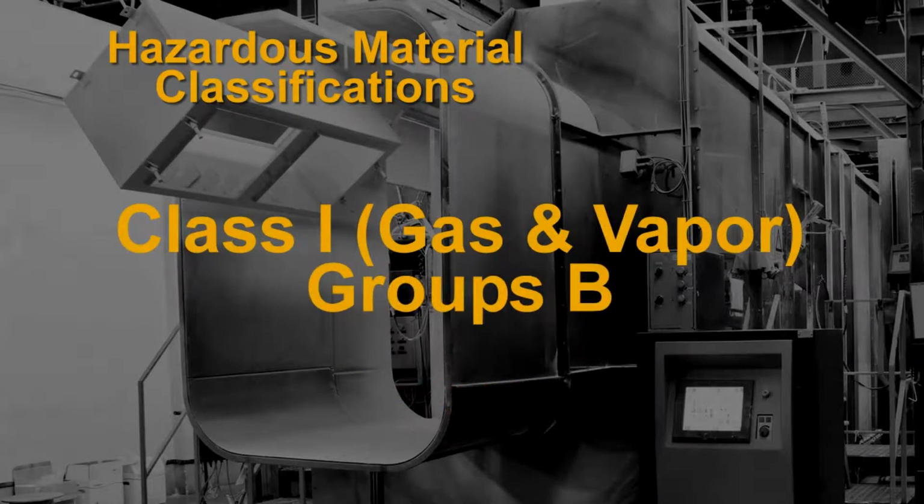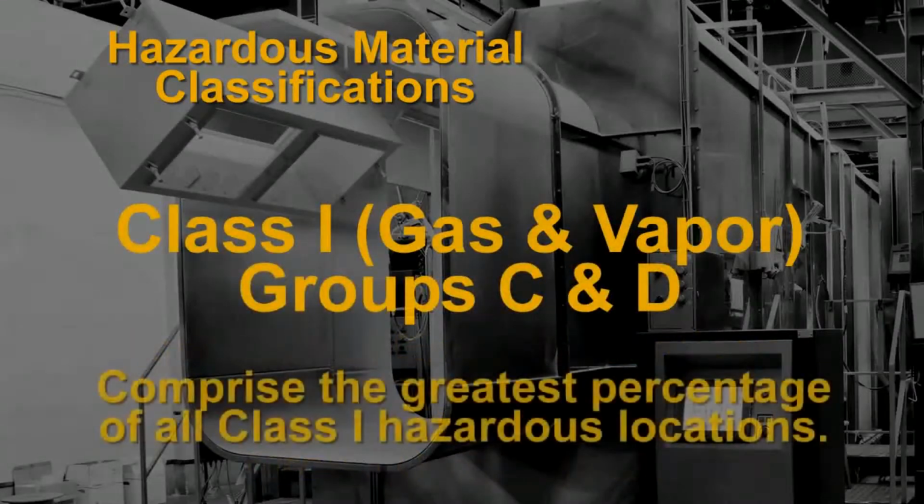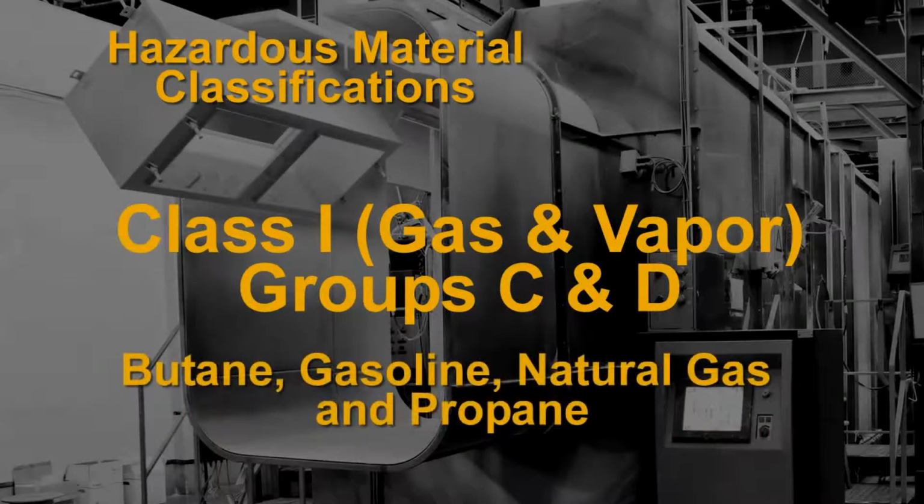Group B is another relatively small segment of classified areas. This group includes hydrogen and other materials with similar characteristics. By following the NEC code, some of these Group B locations, other than hydrogen, can actually be satisfied with Group C and Group D equipment. Group C and Group D are by far the most usual Class 1 groups. They comprise the greatest percentage of all Class 1 hazardous locations. Found in Group D are many of the most common flammable substances, such as butane, gasoline, natural gas, and propane.